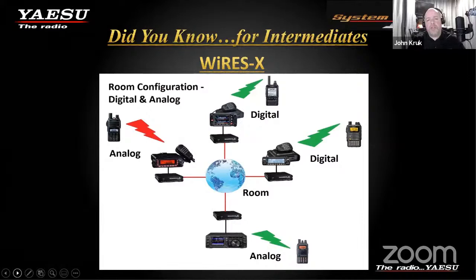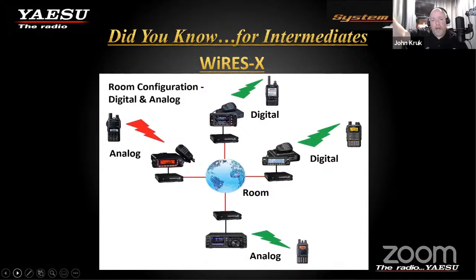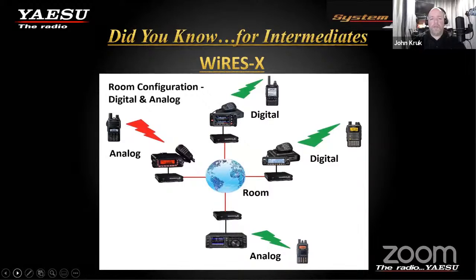Now, one thing that makes Wires X different than all these other types of connection modes out there is that Wires X is a centralized, decentralized system. What I mean by that is that when you turn on Wires X for the first time, you're going to register to the Wires X server. It's going to say, hey, this is node N9UPC, DTMF ID number, this and this and this. Can I go on the Wires X network? And then it will come back and say, yes, you can, or no, you can't, if there's something not registered or something not valid.